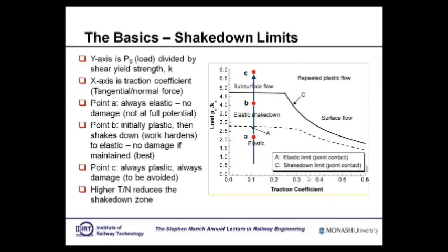What a waste of time. No challenge. Nothing will happen. So you're not really squeezing the material to its capacity. You're playing it safe. On the other side here, you have a repeated plastic flow, and it's called ratcheting. So quite a lot of things, like the material is just oozing out. The material behaves like chewing gum, and it mushrooms and forms corrugations and so on and so forth. Obviously, that is a no-no region because the material won't stop. It'll keep on going like that.